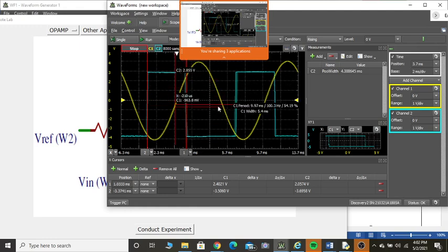Cursor 1 voltage, is the output making a transition from plus to minus? From plus, is it not going to minus at input of 2.4 volt? At this voltage, is the output making a transition from plus to minus? That is VTH. So at a voltage equal to the second cursor, where is the second cursor? This is minus 3.6 volt, correct?